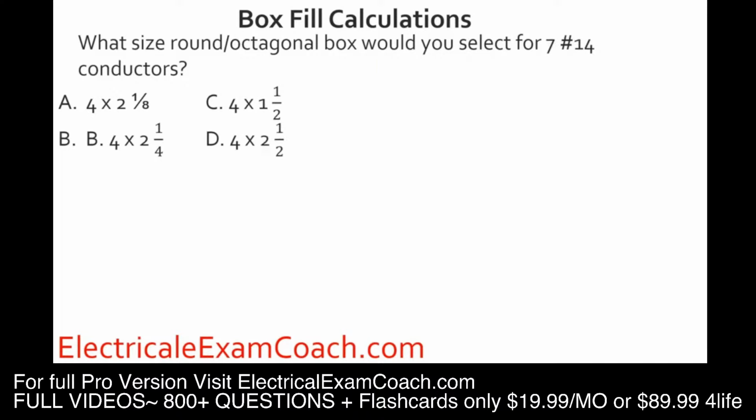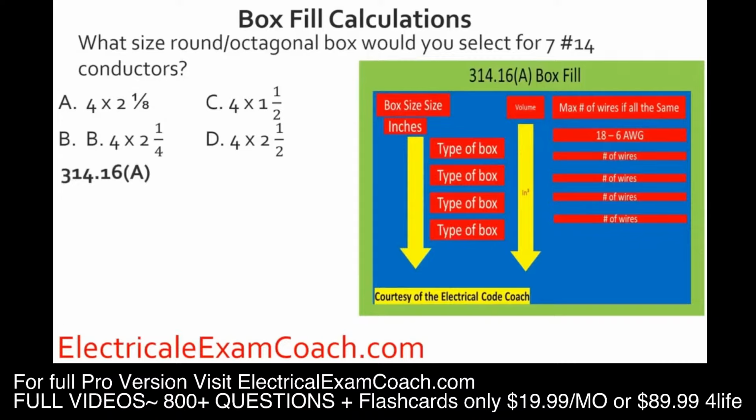What size round octagonal box would you select for 7 14-gauge conductors? We're going to head to table 314.16(A). We're going to start here on the right-hand side, and find our gauge wire. Then we're going to come down and find a box that fits it, and be sure when we cross over that we stay in the right category of box, and we're going to select C.